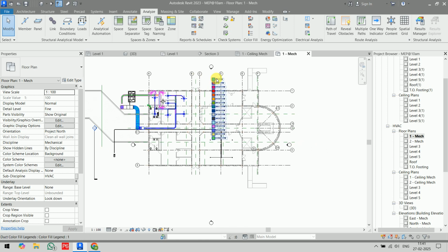What text you don't require? If you require legend, that means you require this one, no? No, I don't want everything. I want some of this. That will not be controllable, no? How will you connect? If you mark the duct legend, then every duct should be included. You will not deselect any type of duct. Okay, it will calculate it automatically with the parameters. You don't have control over that.